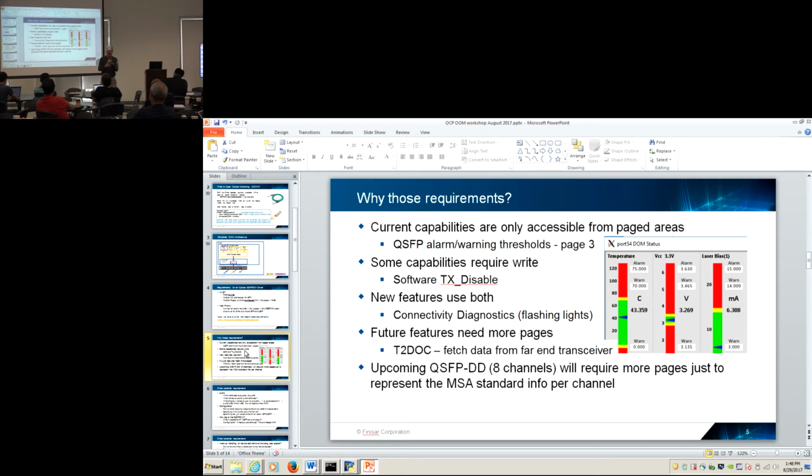The key thing is there's a decoder that maps the address you want to where you're looking for, and a check that says whether it's a legal address. It allows multiple pages, and the right code is in it. That can be lifted and put into almost any driver. The actual I2C layout, this code doesn't know and doesn't care. It gets a call from sysfs that says, here's the port to work on, and away it goes using that port. It doesn't know how I2C got laid out. It calls the standard Linux I2C drivers to do that.